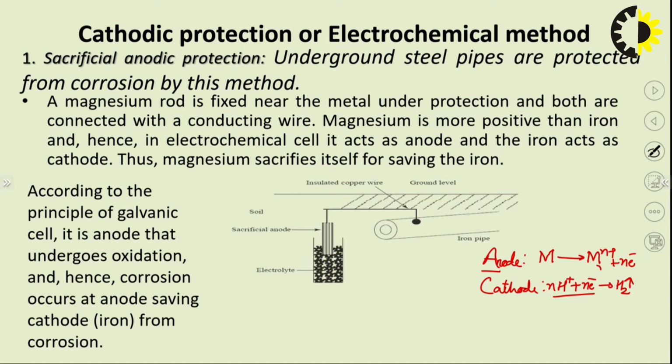Now, by cathodic protection methods, what we do is provide electrons from an external source, and we force our metal not to behave as anode, but to accept these extra electrons from another source and form the metallic structure back. This is the basis for cathodic protection.